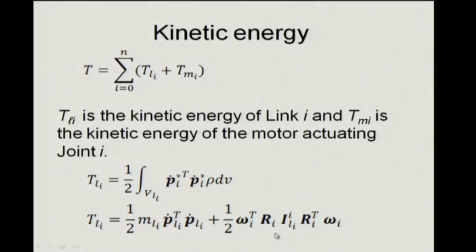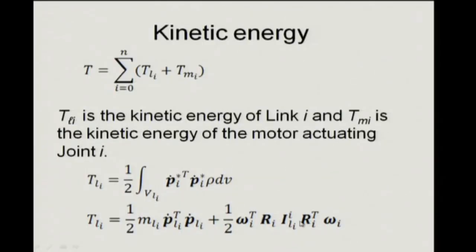So, you need to multiply with two terms, the rotation matrix comes pre and post. That is the standard transform, because you have to go to the link, do that and come back, and this rotation matrix transpose is the inverse operation. Obviously the inertia tensor you can find out, you know enough methods to do that. Otherwise, if you have a CAD model of the link, it will tell you what it is. Number one, it will give you a reasonably good estimate. However, later on you can go back and re-identify and correct the model.